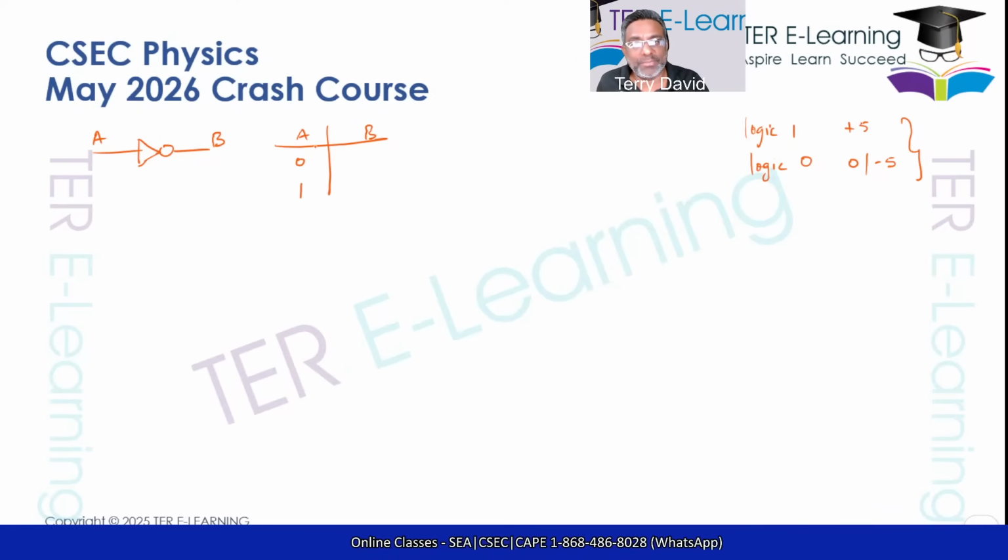So first of all, I'm saying that this here is called a NOT gate. You'll need to know the symbol for a NOT gate, and you need to know what we call the truth table. The truth table tells us how the logic gate works. So if a 0 comes in, you're going to get a 1 coming out. And if you have a logic 1 coming in, you're going to get a logic 0. So that is a simple truth table for a NOT gate.